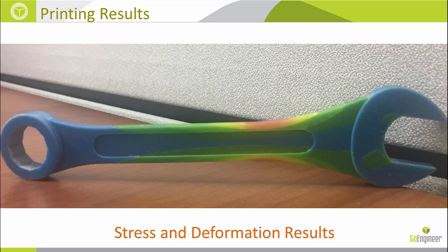You can do the same thing with finite element analysis as well, where you can look at a von Mises stress plot maybe and print it with the deformed shape and specify the color as a distribution. And this can be exported as a VRML as well. And analyze the results. So once again, with the ability to print results, you can take your 2D post-processing tools and make it 3D and analyze it as a team together, or you can also use this for marketing purposes, where you can specify in a more vivid manner how your design is better than a competitor's, or specify your design intent with more clarity.